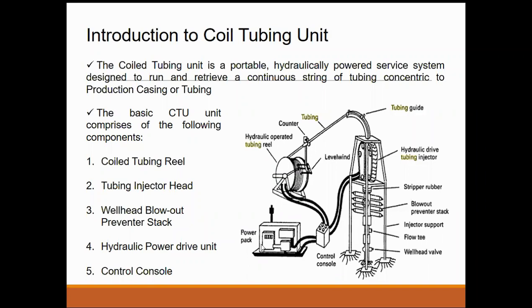So if you pump the sand slurry through it, it will come out in the form of a jet, and it will cut the casing, and it will also cut the cement behind it, and it will also cut into the formation up to a certain length so that your communication with the formation can be established, right? So let's go over this slide.